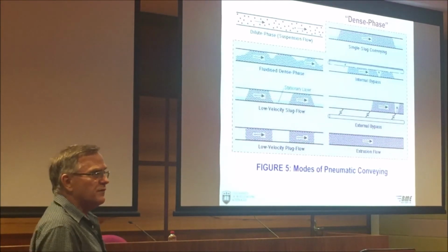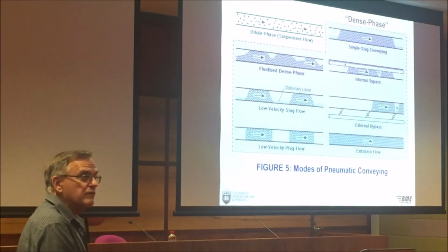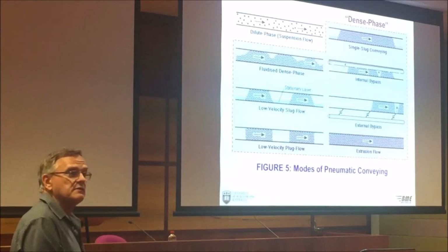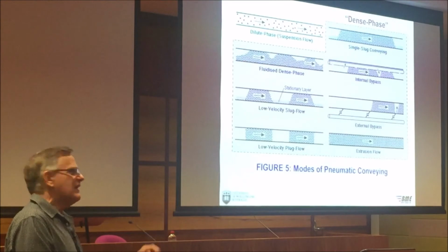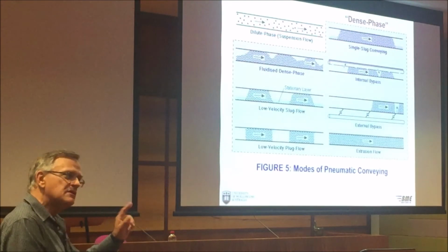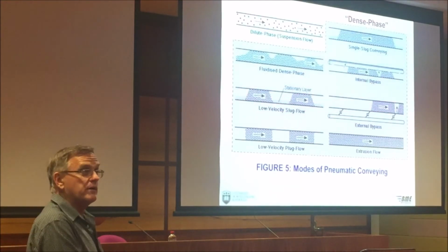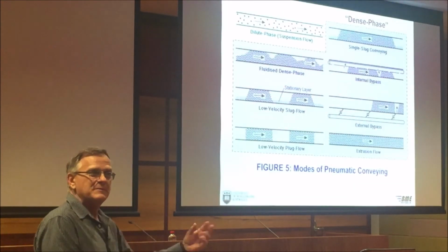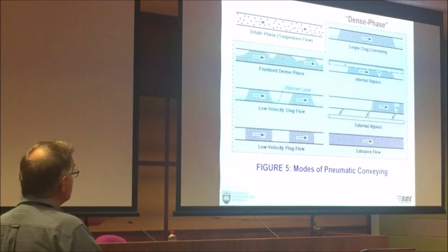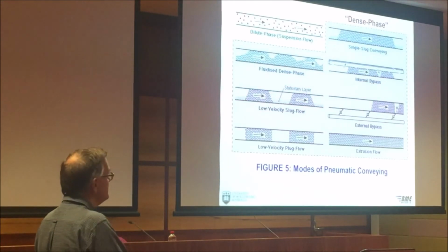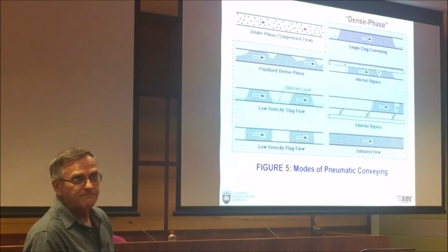Right? And you know, it's quite often you see a nameplate on the pneumatic conveying system that says dense phase pneumatic conveying system. Okay, people believe it. You go and listen to the pipeline, that's dilute phase. They say, no. The nameplate says dense phase. I said, hey, rubbish, have a listen. It's dilute phase. So people spend the extra money to buy a dense phase system, and the supplier hoodwinks you into thinking you got a dense phase, but it's a dilute phase system. And the reason they do it is because these are much easier to design than these systems. So if you want a dense phase system, you pay extra money, make sure you get one.